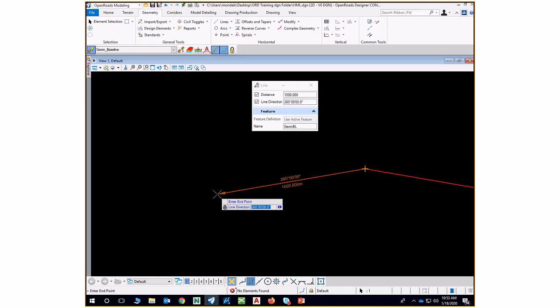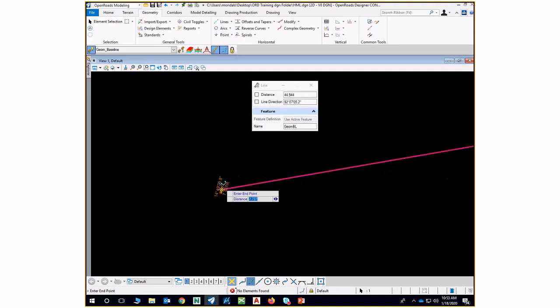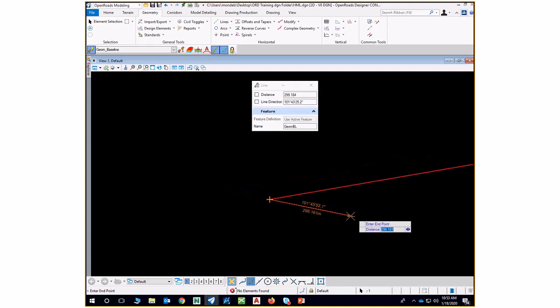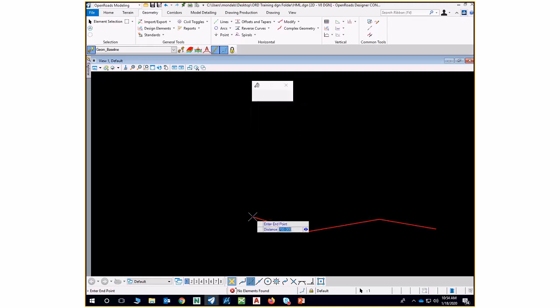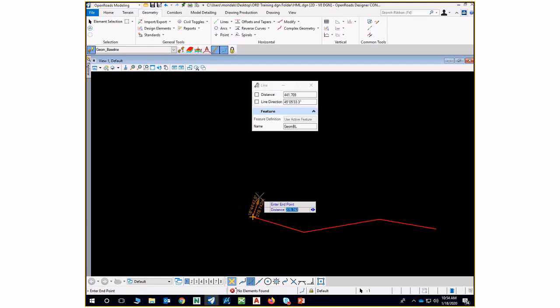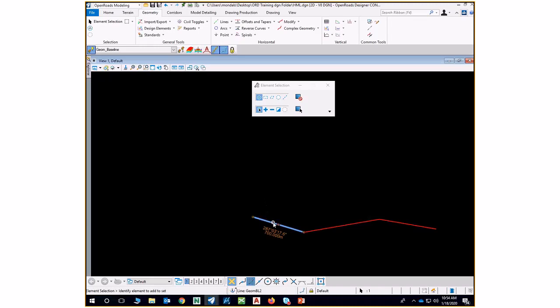Let's click it here, a data point. Now you can see this. It does not go to the select start point, but it is asking you to enter your end point again. Let's arbitrarily click anywhere like 1000 meter, or let's say 750, 700 meter, and click it here. To finish it up, you can just right click, so it will come to this point, enter start point, and press escape. So you have some lines.